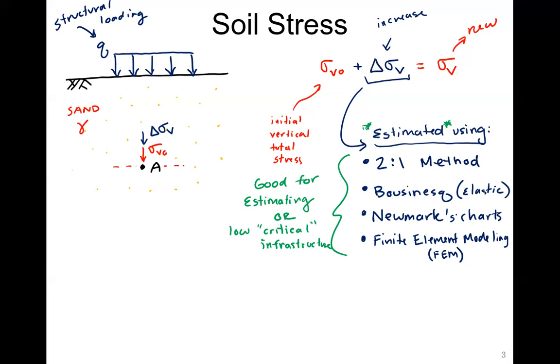I've used like the Wawas or almost like the cookie cutter designs where the site conditions are well known. You have high confidence as an engineer that the site conditions are represented by your analysis, and this increase of stress that you're estimating in the soil layer, if you're off by 100 PSF or, you know, if you're off by a little bit, it's not going to be a big deal for the life or the comprehension of the whole project.